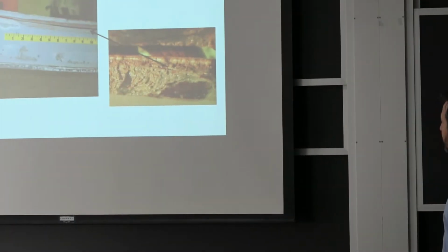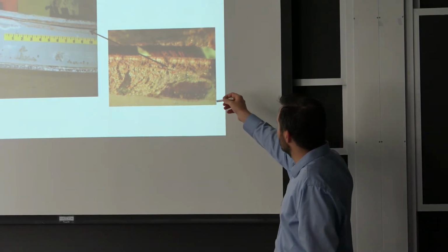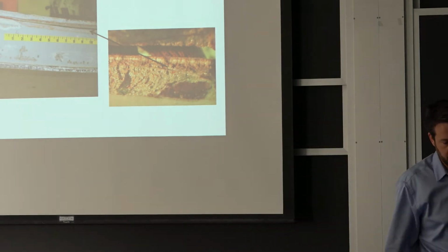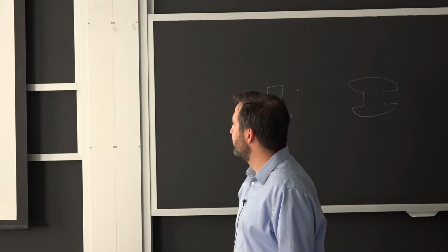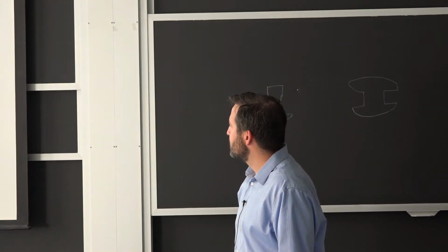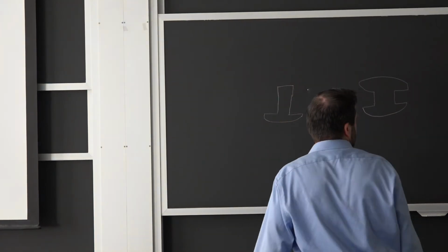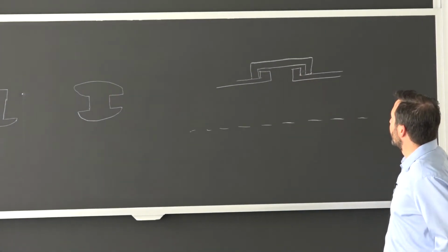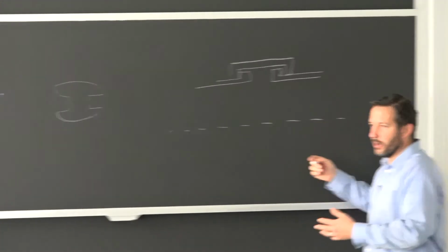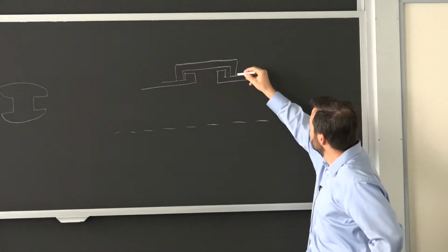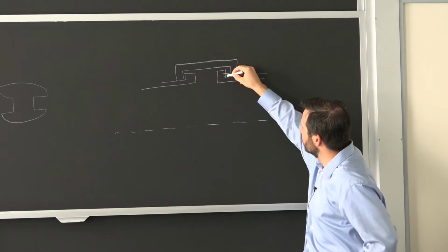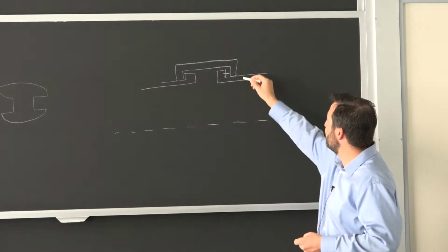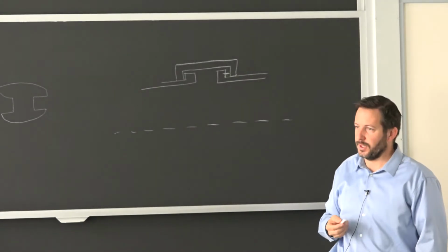And the main finding from looking at the fracture surface was there was one initiation site, so one spot that didn't work the way it was supposed to. What happened is when they tried to engage these things, there was one spot where either there was debris or the pieces were a little too far apart, so it didn't get all the way in. So we could see the bearing mark kind of halfway here on this component, and so there was a lot more bending in that corner than there would have been if the clamp was put on properly.